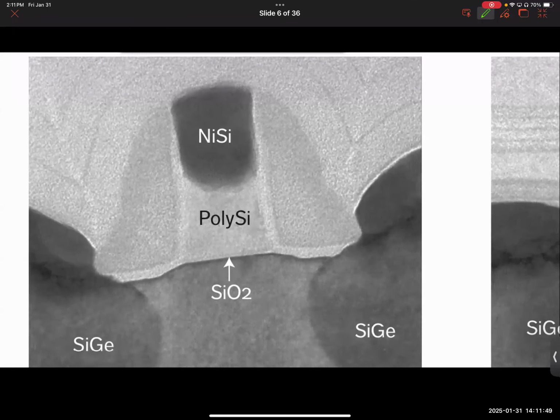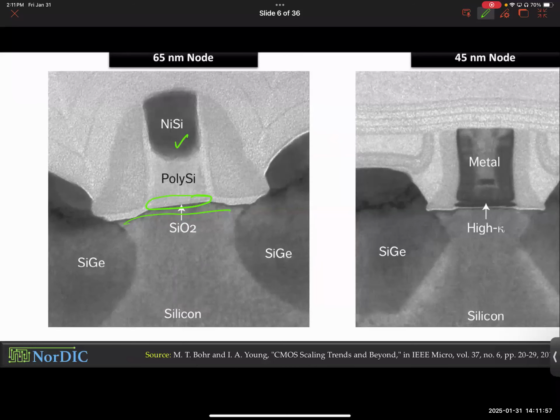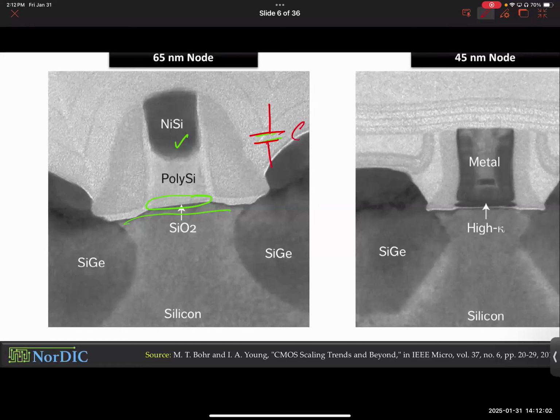You guys ready? So silicon dioxide is an oxide. You have a metal here, you have a conductor here. So essentially, you have a gate capacitance. Let me just draw it here. You have a gate capacitance, which is C_OX, oxide capacitance, okay? And then you have a depletion capacitance here in the channel. So basically, we represent that as surface capacitance, C_S, or substrate capacitance, or semiconductor capacitance, whatever the S stands for. So M is related to the ratio of these two capacitors plus 1.